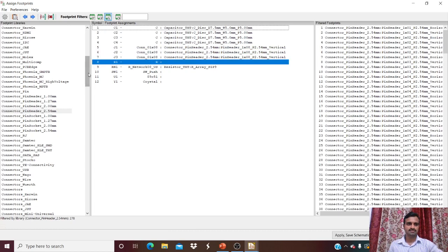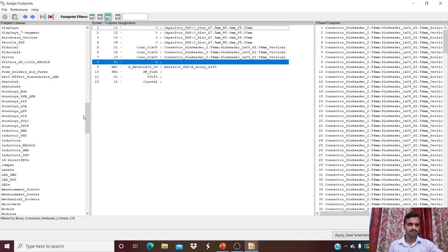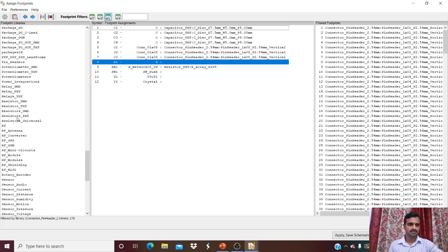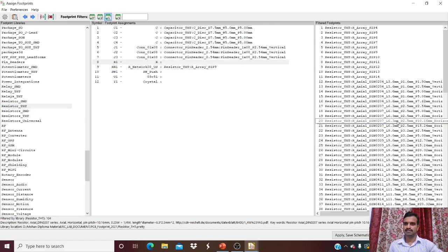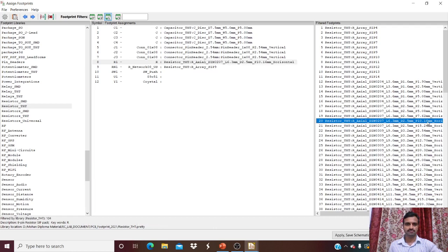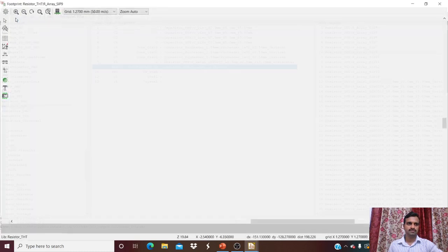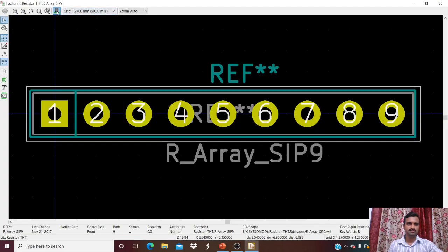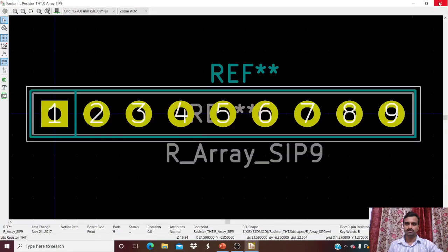Okay, now select the resistor. I'll select the component footprint for the resistor. Go to the resistor THT through hole component, then get the axial resistor with the length of 6.3 mm and pitch of 10.16 mm. Next get the pull-up resistor. Already it will be selected, so you can view this pull-up resistor on this footprint resistor. You can view the pull-up resistor 3D view also.